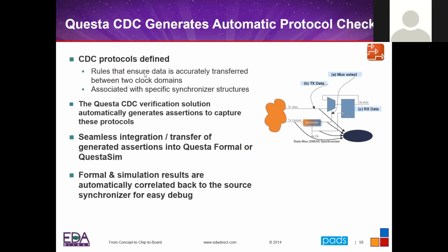So as I said, an example here of how you would synchronize a bus is, normally you would be just holding the data that you currently have. And then when you have data you want to pass from one domain to another, you put it out here, you pass the control signal that says, go ahead and sample that.